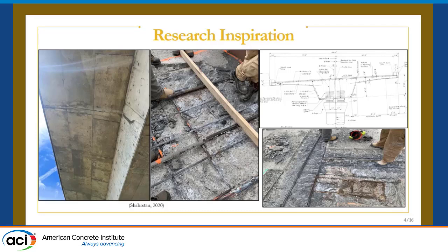So this was a bridge that was on the typical 20-year maintenance cycle, and when we showed up in 2020, you can see the effects of corrosion and the lack of maintenance on this bridge structure. I also wanted to showcase the underneath, that's the soffit of the cantilever. It's a pretty lengthy cantilever wing. It's 12 feet or 3.6 meters metric.